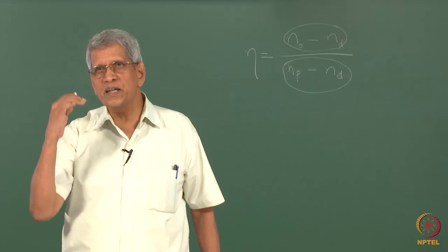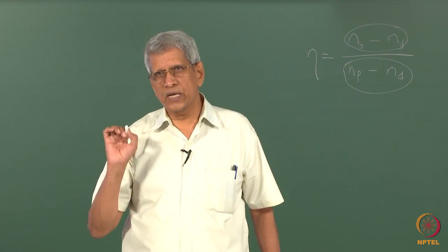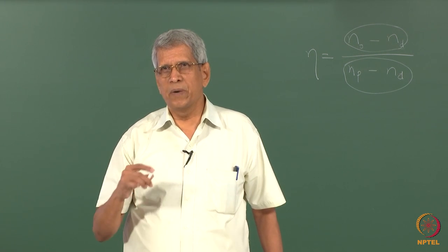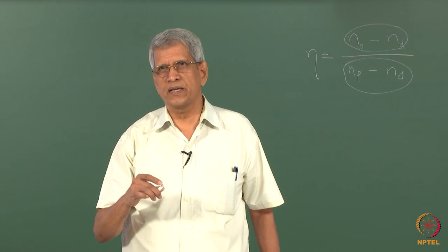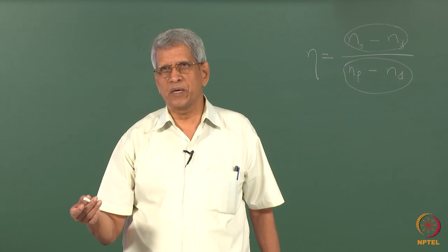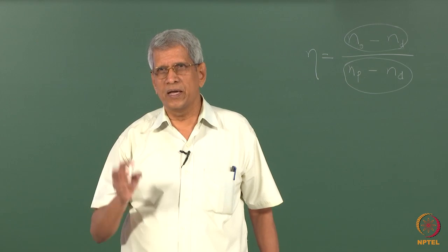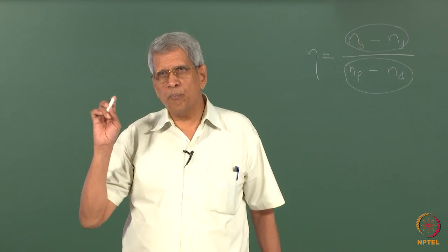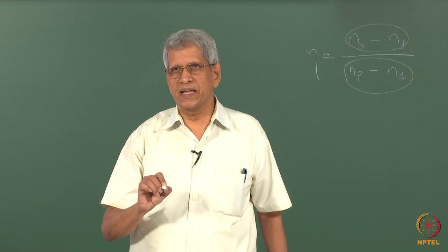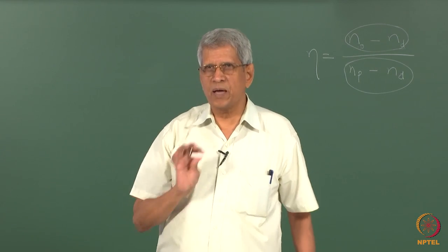First I wanted you to understand that this is the type of defect which can form, because ordered alloys are the ones which quite often we deal with in metallurgy. But in ordered cases compared to disordered cases or compared to ionic cases, there are types of defects which are present. Before introducing them, even in a perfectly ordered alloy, where no point defects are generated, even then we can have a disorder in the material. Some defect could be there. These defects are the anti-site defects. That is what I am trying to explain.